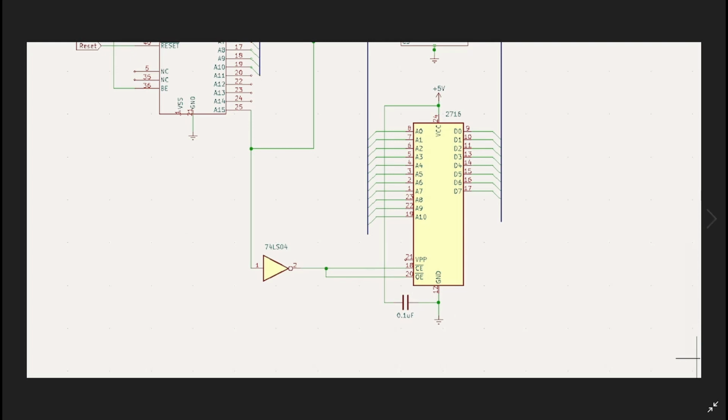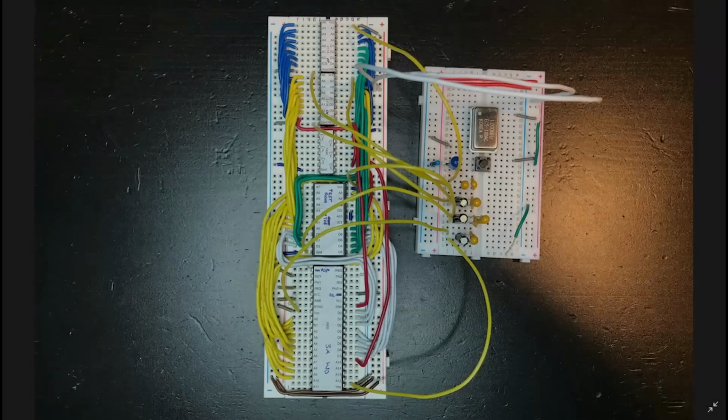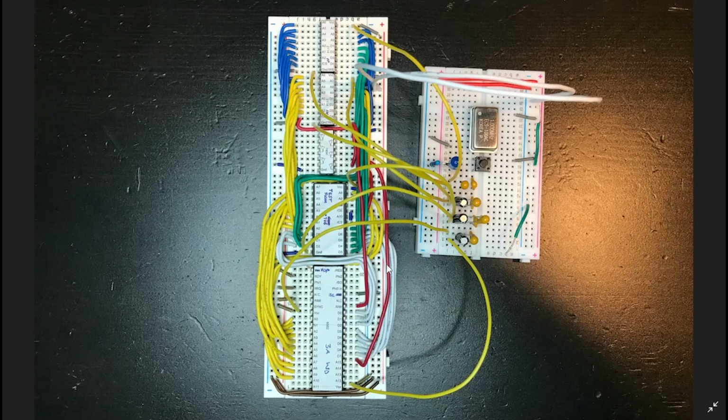So that's what it looks like there. On the actual breadboard, I've just done jumper wires for this simple circuit. I put in a few different kinds of capacitor. I was just playing around with some different values. We've got some electrolytic, some tantalum, and some ceramic capacitors. The ceramic capacitors, 0.1 microfarads, are perfectly fine for this here.